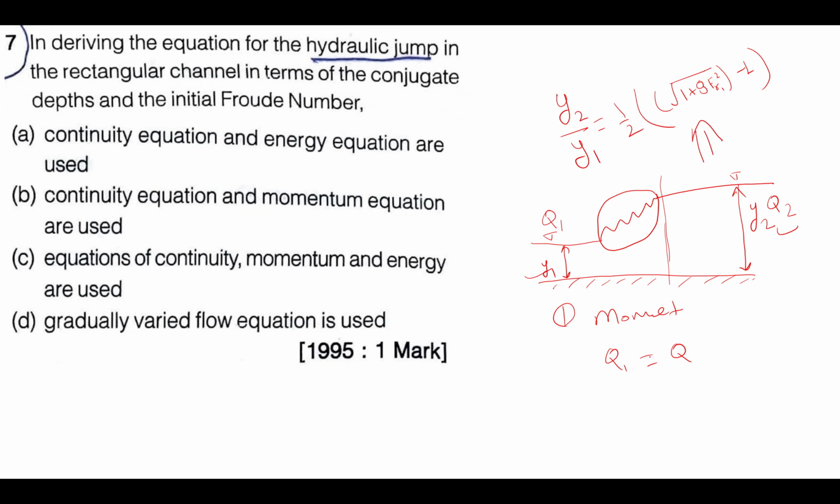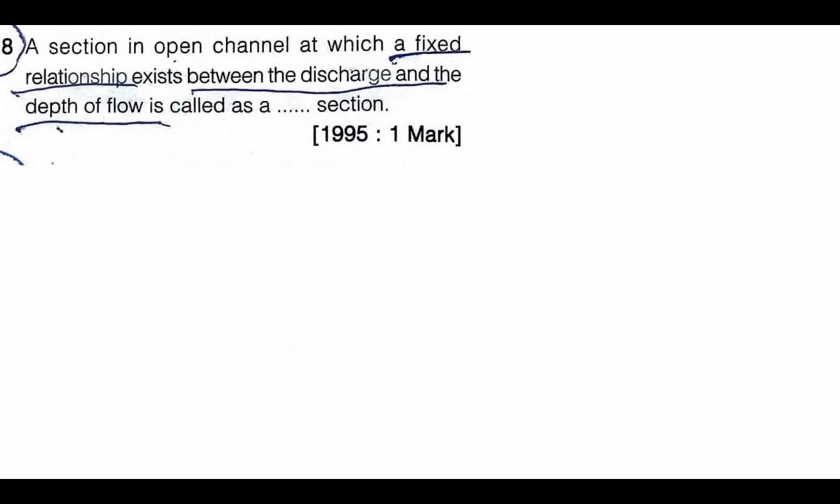Why can we not use the energy equation? Because of the energy losses in the formation of the jump. So option B will be correct for that. Continuity equation as well as momentum equation you can use.